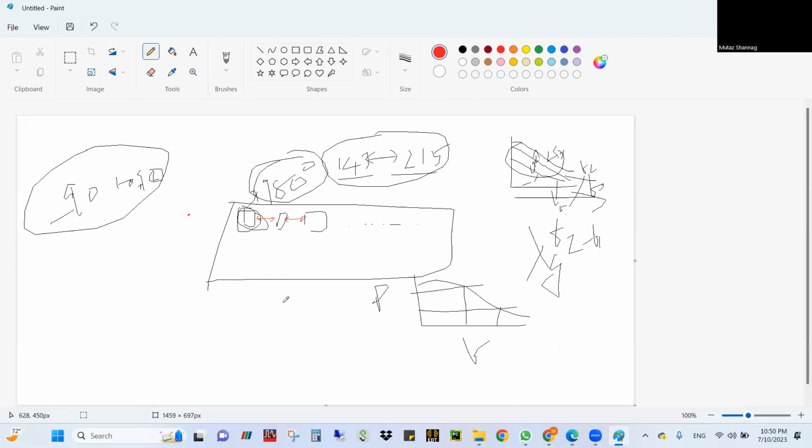No, no. See, there are two ways to feed the unit cells, any patch or any antenna, basically. One is direct feed, which is normal microstrip patch or whatever it may be. The other one is spatial feed. Spatial feed is where you are exciting with the plane wave input basically, or whatever you are emulating that. So spatially, you are keeping the feed, and then you are illuminating the elements basically.